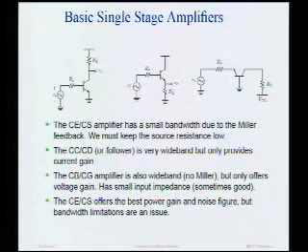What are some other problems with a common source amplifier? Anyone? It's all review material, right? Why not just go out and build all our amplifiers with a common source amplifier? Use low source impedances so we have lots of bandwidth. Yes, Mike. I don't quite remember exactly, but it has to do with output impedance. Okay, that's a good point. Let's not worry about that now. We could always buffer. We could put a buffer in there and get any output impedance we want. What are some other properties of, okay, in the middle?